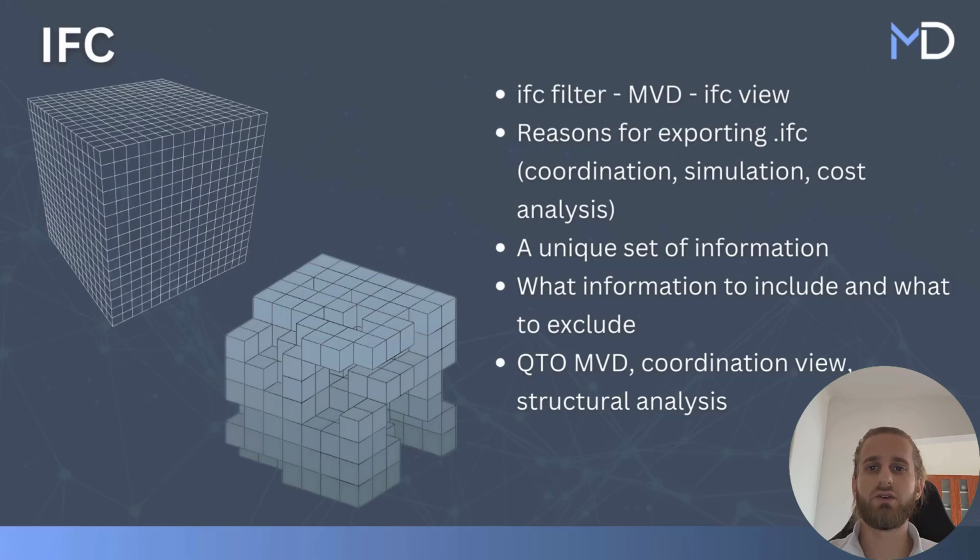You have MVD.xml today, which means the following. If an investor or you as a BIM manager know how to work with MVD, you can write in an Excel table what you want the person to export to you. Send it to the person who works, for example, in Allplan, and that person will import that Excel file. When exporting, they will export exactly what you wanted. That's a great thing with MVD.